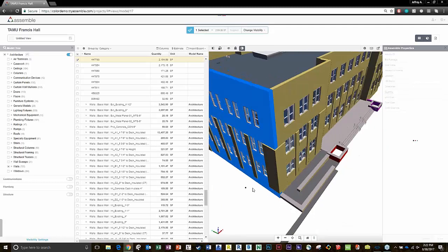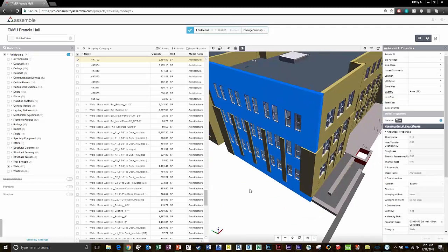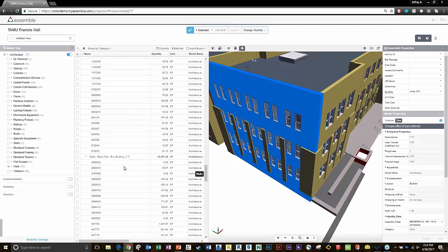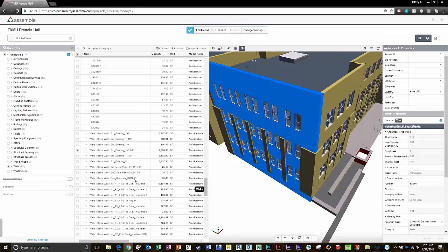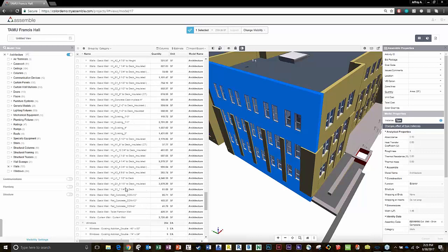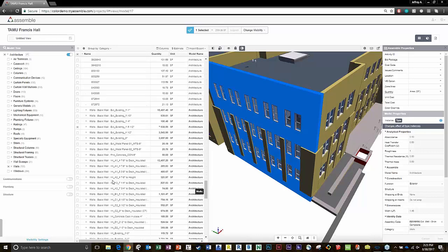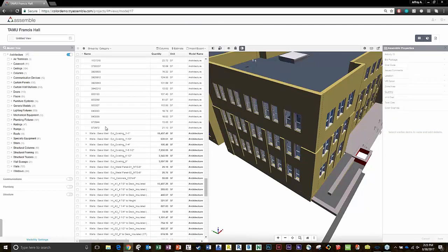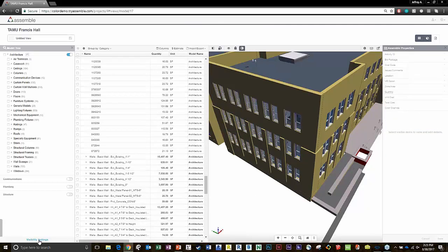So to do a quick exterior wall takeoff, what I typically will do, again for non-Revit users, is explain how to look for information on how to filter things. A perfect example is exterior walls. Now, I'm familiar with this model, so you can take my word for it. The way this design team works is they have EXT underscore before all their exterior walls, and for the interior walls, they have INT underscore. They might be using the correct functions, but I know for a fact, because I'm familiar with this model, that INT is used for interior and EXT for exterior.